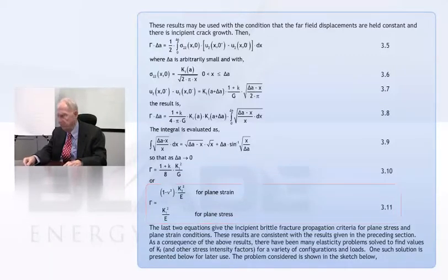If you think about this sort of stuff, you're talking about the tip of a crack. The radius of curvature at the tip of a crack is essentially 0. And if you wanted to have a solution, what kind of a solution would you work out? Well, the thickness of any real plate is much greater than the radius of curvature at the tip of the crack. So I would always choose to have a plane strain solution. Now, as I mentioned, that early solution was one for plane stress, and that's something we've got to keep in mind so we can be critical at the proper moment.